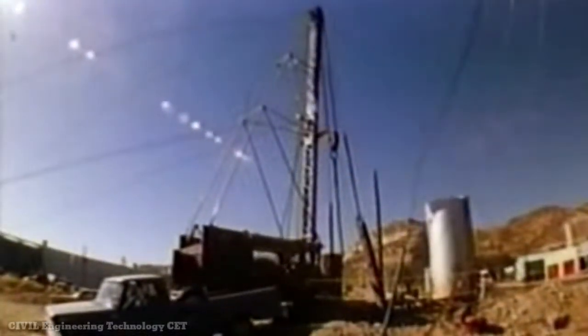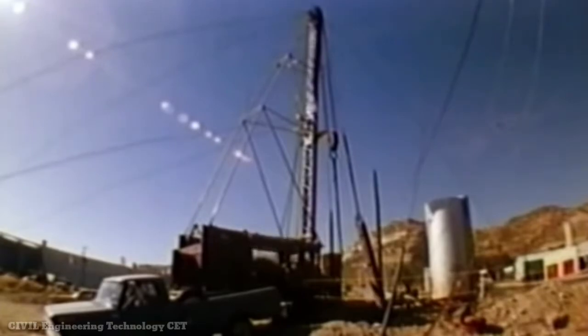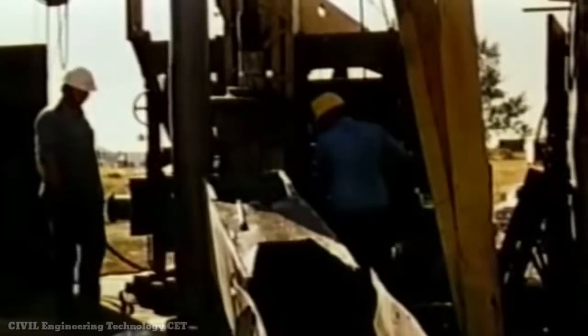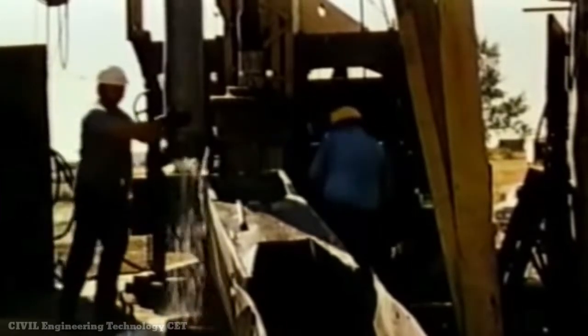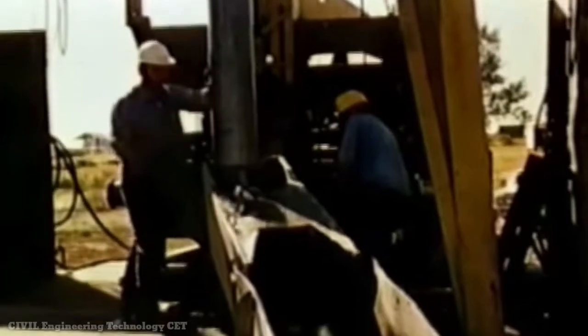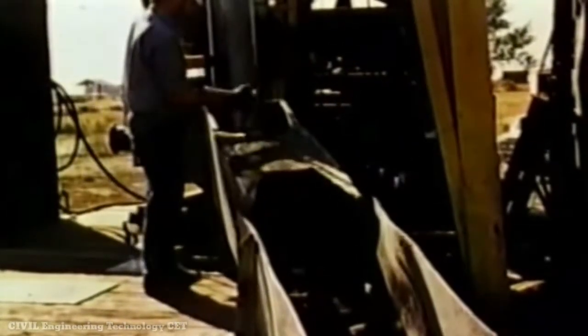Another drilling technique uses a pounder machine, usually referred to as a cable tool drilling rig. With this method, a heavy bit is attached to the end of a wire cable, is raised and dropped repeatedly, pounding its way downward. Periodically, cuttings are bailed out of the hole. The method is slow and in most places has been replaced by rotary drilling. The cable tool method is responsible for millions of successful wells around the world.